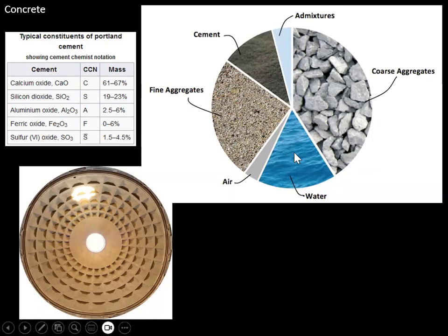Now, there's a misconception about that too, which is, I mean, if you don't know any better, you might think, oh, okay, you can pour the liquid concrete and I guess all the water is going to evaporate away and leave the hard concrete. That's not how it works, right? How it actually works is this Portland cement undergoes a chemical reaction with the water. So whatever water was initially in it in the liquid form is still in the cured concrete. It's just a chemical reaction that binds it all together. Oh, and that process can take years sometimes.